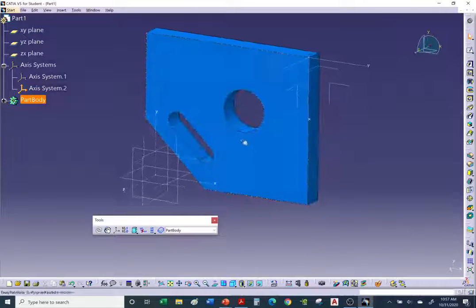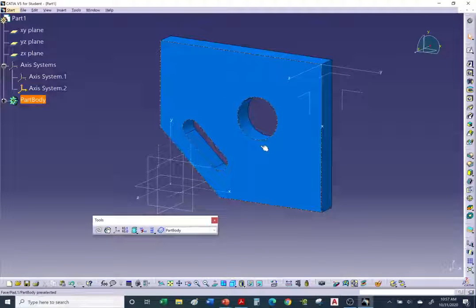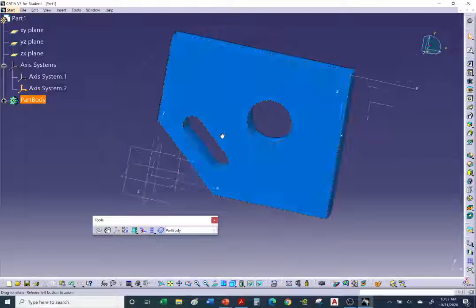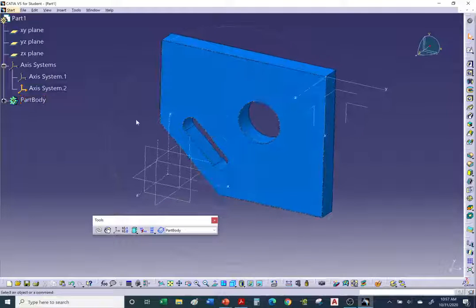So sometimes when I download something from a catalog, or maybe I have to model something from a catalog that we can order for a machine shop or metal forming shop, like clamps, for example. When you download it, it'll come in separate part bodies, or if you're modeling it on your own based on their dimensions in their catalog or their website, instead of having to model different parts, I'll just do one part with multiple part bodies.